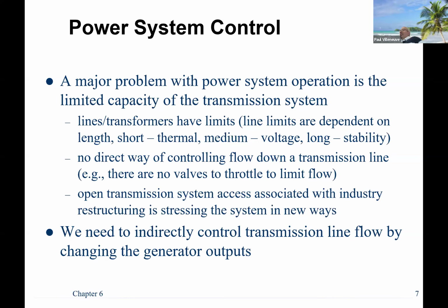And there are different limits, called short-term emergency, long-term emergency, and drastic action limits. For the long-term emergency, you get 8 hours. Short-term emergency, I think you get like 30 minutes to an hour. The drastic action means you've got 15 minutes to fix it, or else this transformer is going to catch on fire, perhaps.